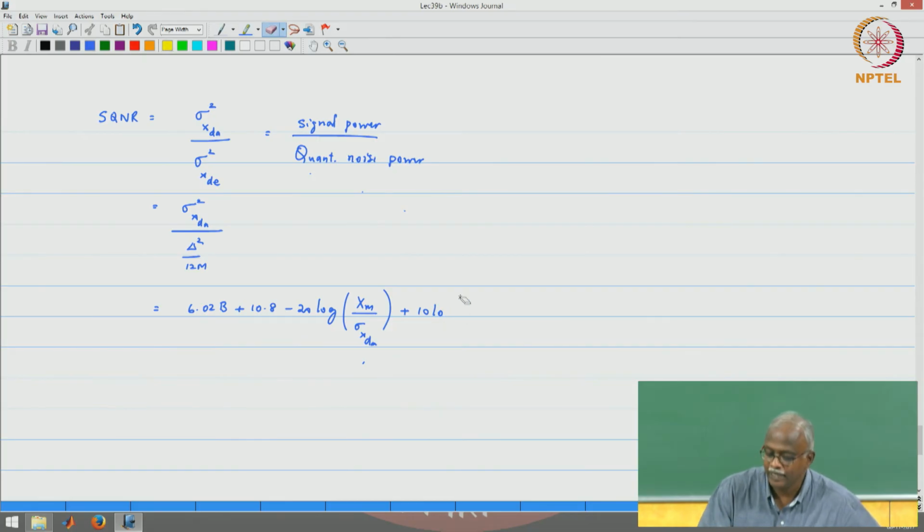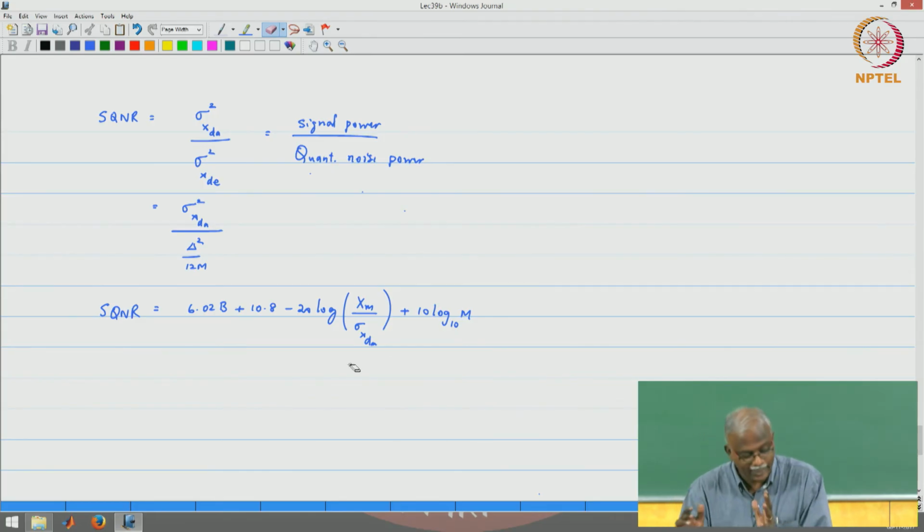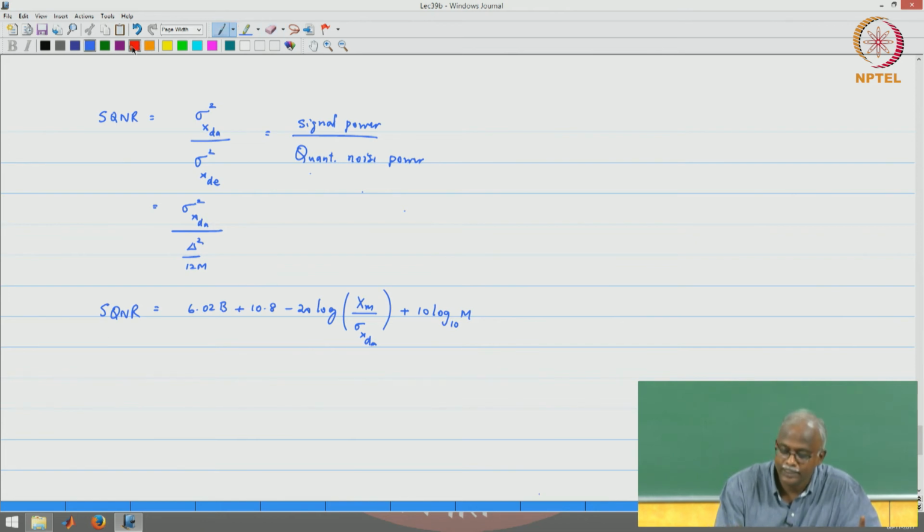That factor of m has now entered the picture. So, by increasing your oversampling rate, you not only reduce the complexity of the anti-aliasing filter, you actually also benefit in terms of the noise. Here is a very important element. We have a thumb rule.